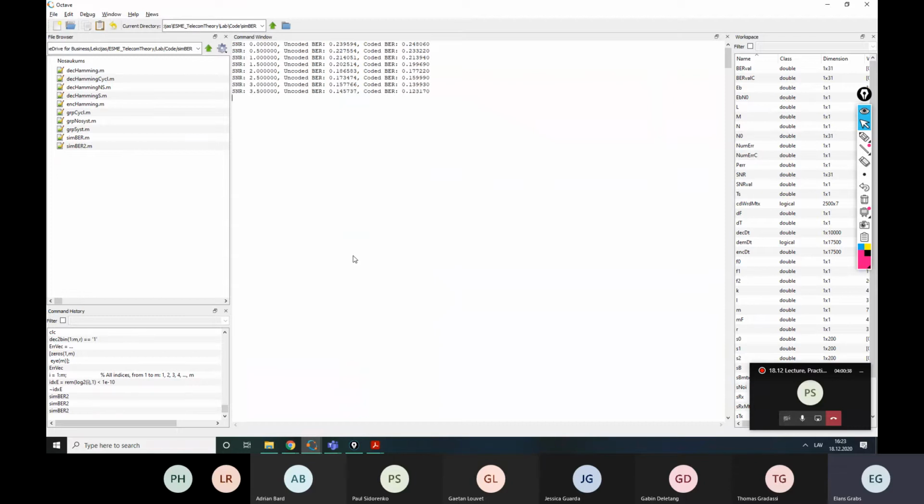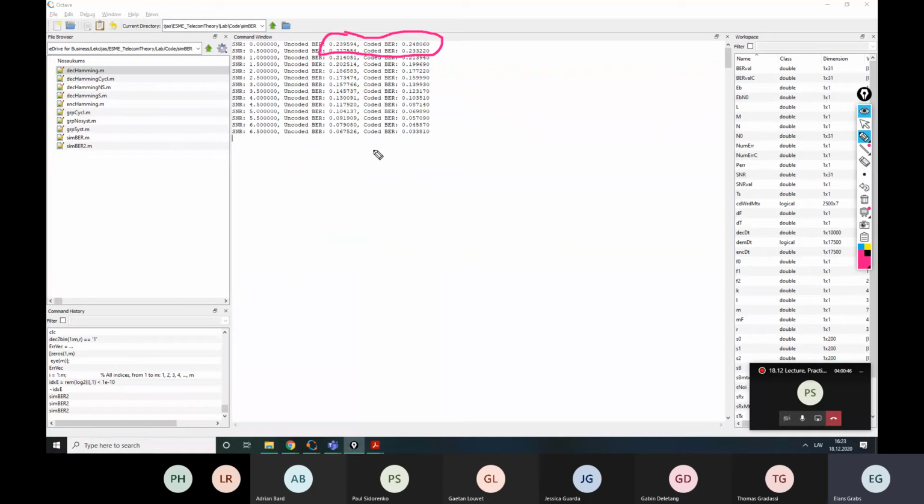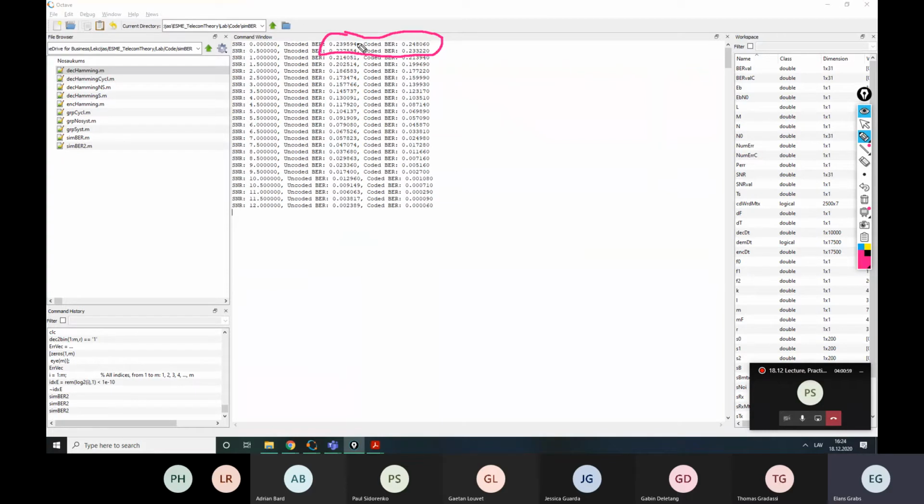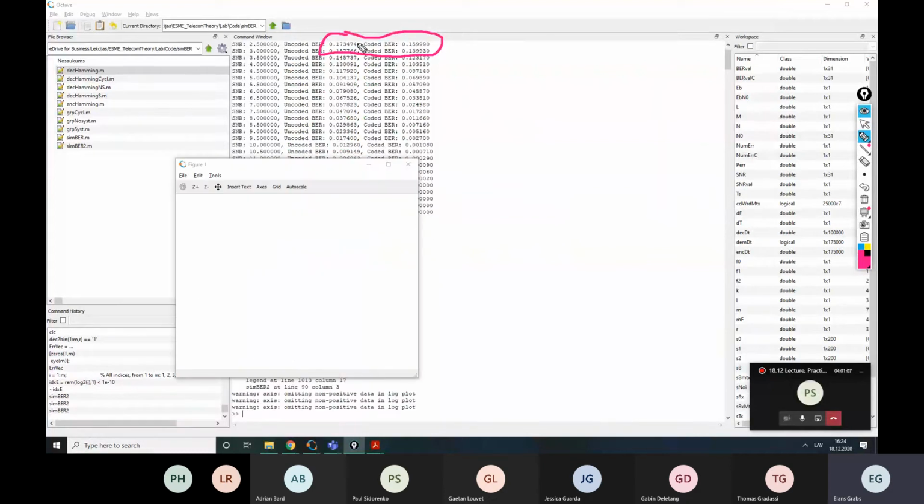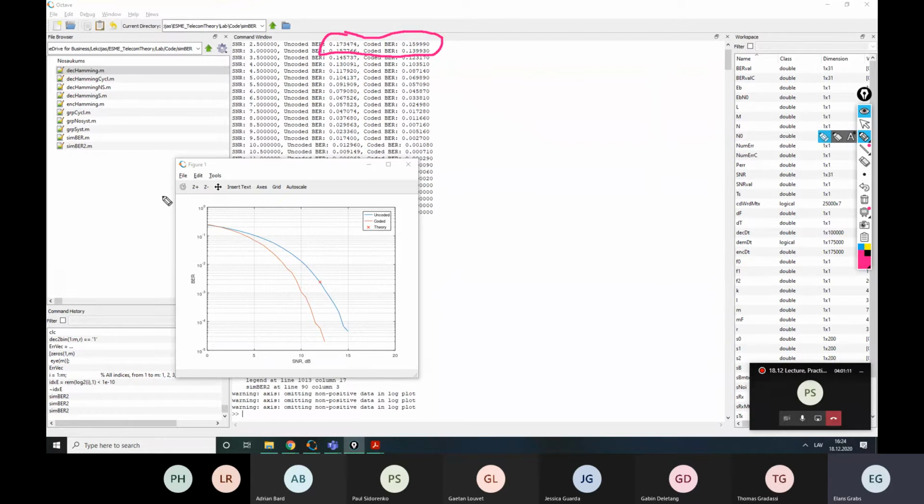Now, if you look carefully, you might find out that in these 2 cases, the coding did worse for us a little bit, because this is a very bad channel, right? Nothing can really help. Well, not let's just say nothing, because as you know, Shannon has proved that you can actually improve this channel. However, it would take a ridiculously inefficient code, but it's still possible, right? So if we zoom this out, you can see that for Hamming code, for this low signal to noise ratio, there is a worsening. However, this is observed very shortly, and for your case, it might be longer, but still what you need to understand is that at any rate, this system is just unusable.